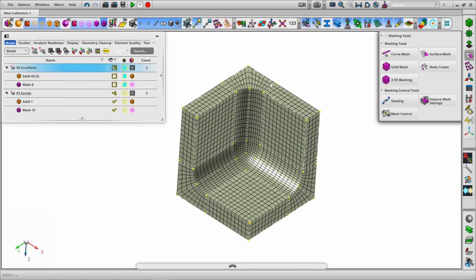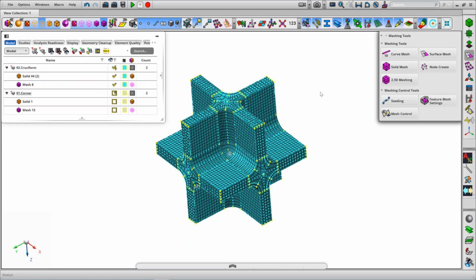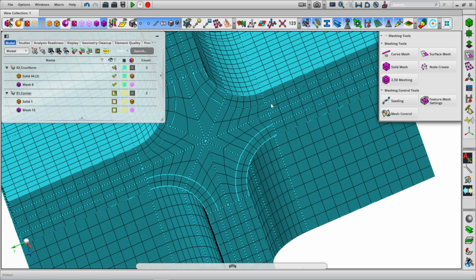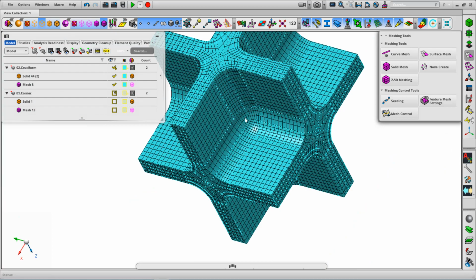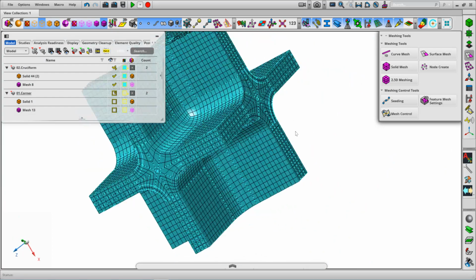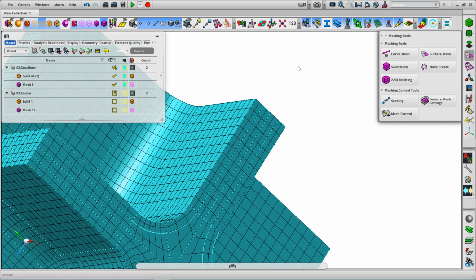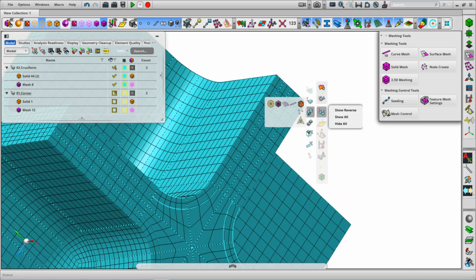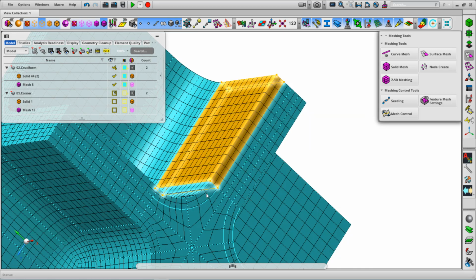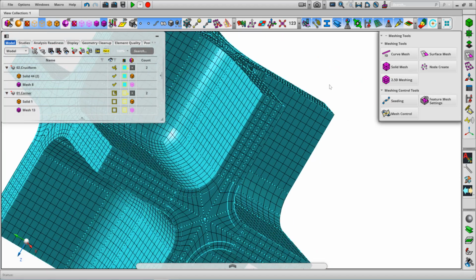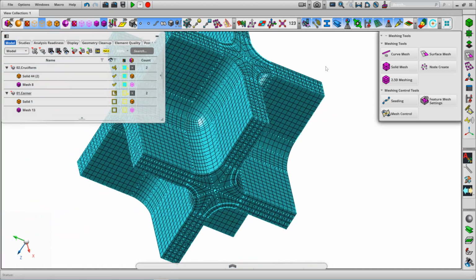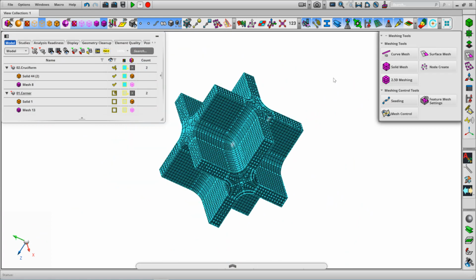Here's one I made earlier, as they say. So here we've got a pretty complex geometry, with cruciform fillets in all regions. I've actually split this as well to give us, let me just show you, these bounding partition regions as well. So the elements close to the surface are perfect quality, or as close to cubic geometry as you can get.